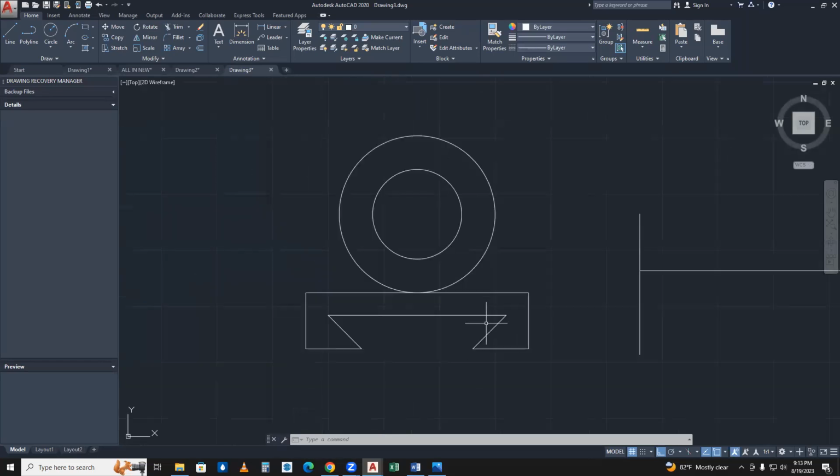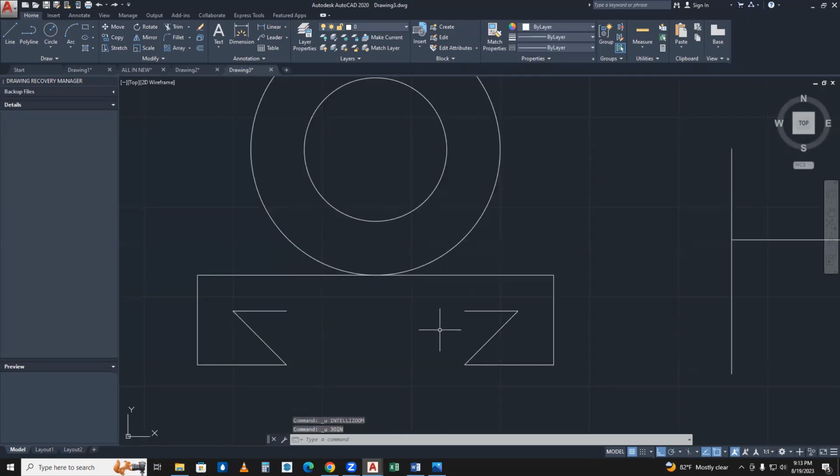Okay. So should be clear with the extend. Extend we can't use anyways. We'll check whether it's possible. So I'll undo. So I am selecting this. I'm typing EX. Enter. See, it does not intersect with the bounding edge.